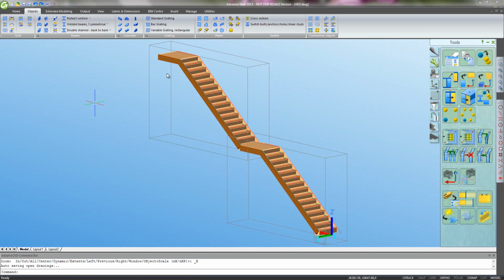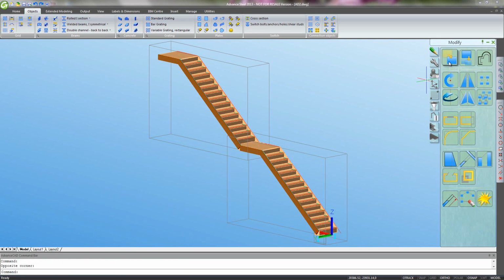Now for the handrails, we'll copy those base beams up and change the options or the properties. So I'll just use a simple copy command. And we'll start with the ones on the landing, because on the horizontal they'll be at a different height on the slope. So I'll make those 1100 higher for the handrails on the landings. And then we'll copy the sloping rail 900 up,